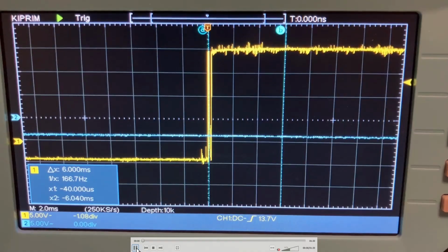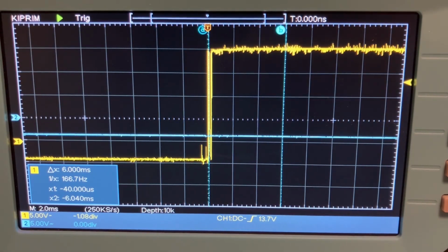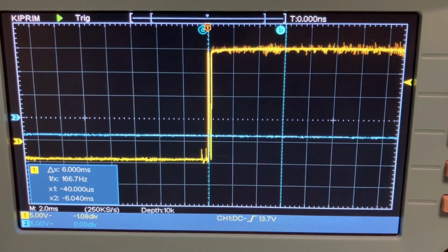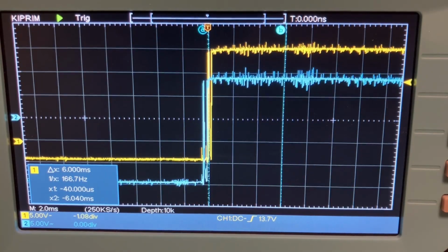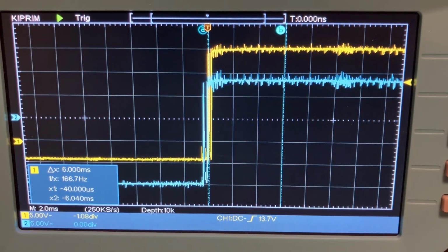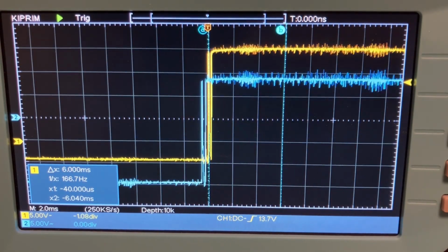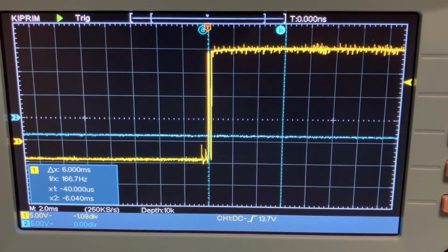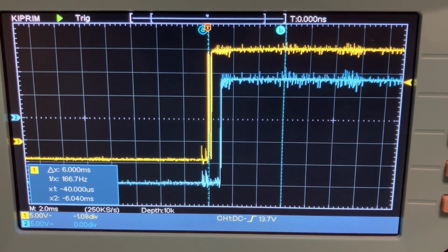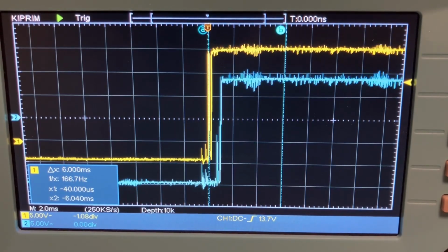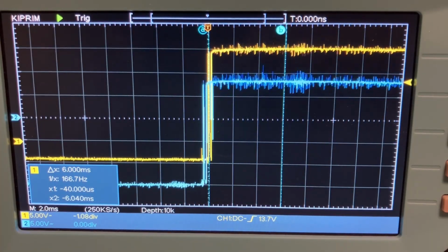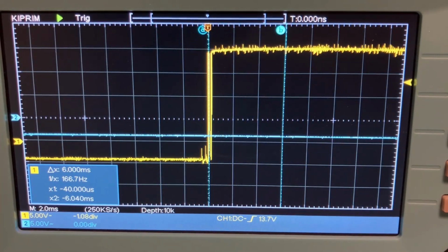And when we start the measurement, then we see that most of the relays, so the first one, are switching at the same time as relay number 15. This is a little bit faster. This is also a little bit faster. This is a little bit slower, I would say 1 millisecond, but this is not a problem. This is a little bit faster.